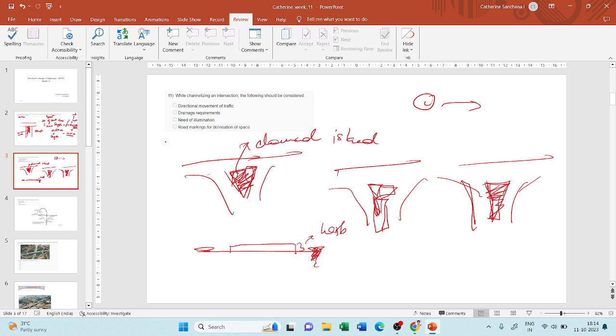Okay, and you should not use very high curbs, okay, with angled iron frames. So you have to provide curbs but not very high curbs. And then in case of a divisional island, what we saw earlier, the approach width shall allow the smooth movement of traffic.